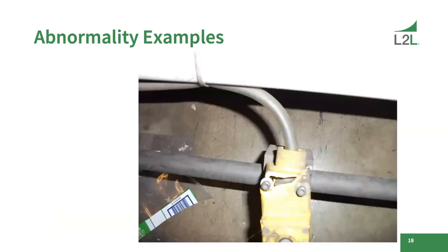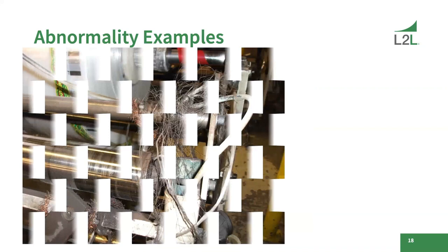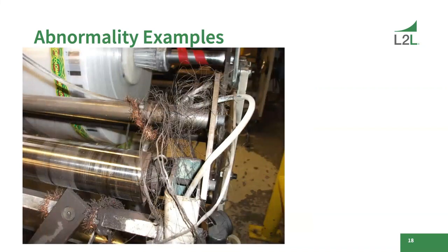Small cracks, broken wires, frayed wires, all of that. It can be a safety issue. It can be a quality issue. It can be product related or whatever. You want to begin to really look at this machine as you clean and inspect and find those abnormalities, and then go get them fixed, because all of this is going to be downtime at some point later on in the timeline, and it's just going to cause more heartache.